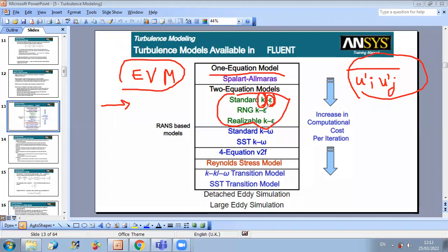And we'll see that in K epsilon, we have several types, because what we do is make some modifications in the equation. The idea is that whenever we want to treat turbulence, we add an equation for K and an equation for epsilon. As I told you, these equations are empirical. We do experiments in order to get empirical relations relating our turbulent variables. And in this differential equation of K and epsilon, we need constants.